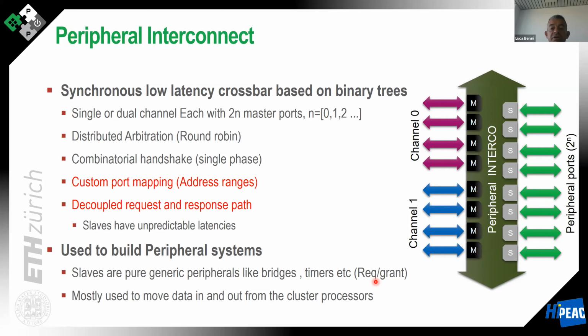In this case, there is a difference because peripherals are memory mapped. The interconnect has to provide access to contiguous addresses into the same target port, since the target port now is a peripheral, and all the registers corresponding to that peripheral will be in a contiguous region in the memory map. So we cannot apply word level interleaving here, otherwise the addresses of our peripheral will be spread to several target ports, which is not acceptable. We have a peripheral with a single target port. So the address multiplexing scheme is not word level interleaved, but the topology of the interconnect is very similar.